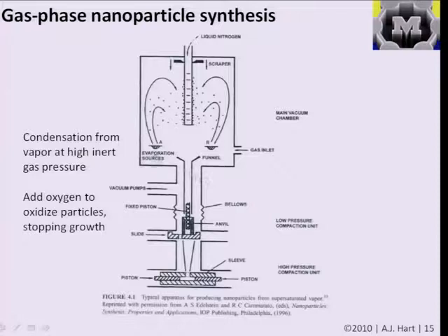and you say, for example, have two sources of a solid material, and this is analogous to the syringe of precursor on the previous slide, and you would evaporate the material into the gas phase such that you can then condense it or collect it on, for example, a surface which is cooled. And depending on how much of this source you evaporate, you may create a sufficient pressure of the vapor of this solid material in the gas phase to nucleate the structures in the gas phase, or you may just deposit it on this cold surface and then have the sizes of the structures grow with time there.